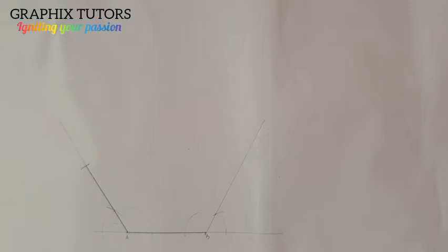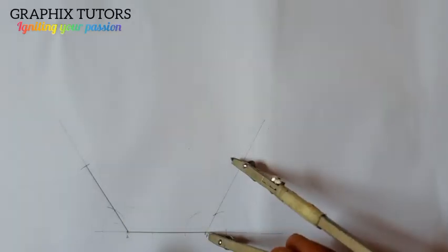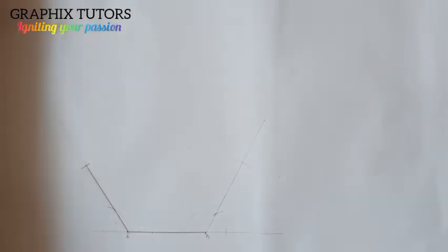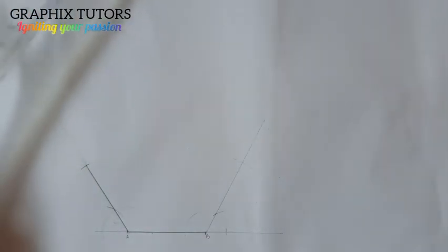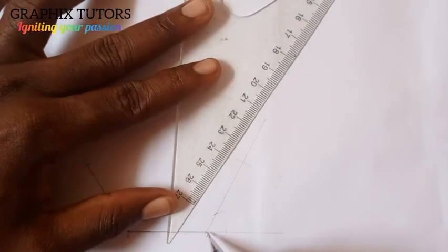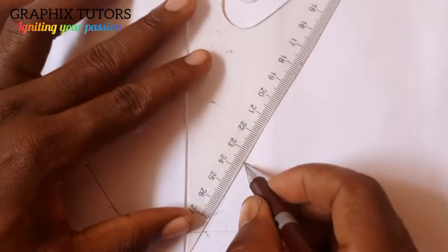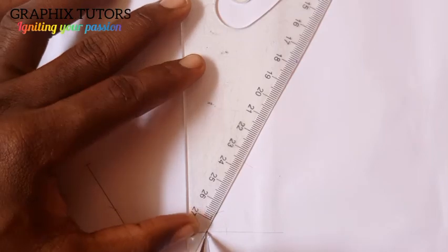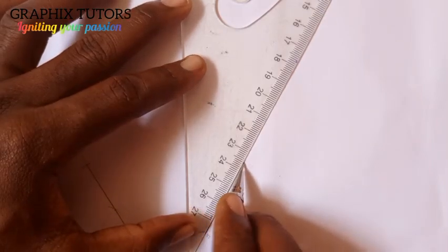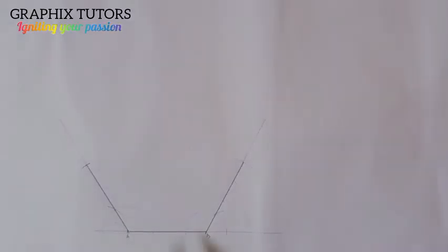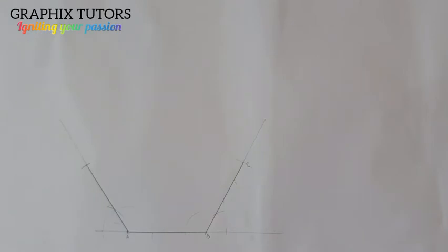Now I'll measure from A to B also, because we say the sides of the hexagon should be 40. So every side should be what? 40. I'll come also here, I'll slash my arc. So where it meets, right, I am going to place it here on B, and I'm going to take it. You can see that? So this AB, I'll call it to be what? C. Is that taken? Now the next thing I'll do after I've gotten these two sides, I'm going to move